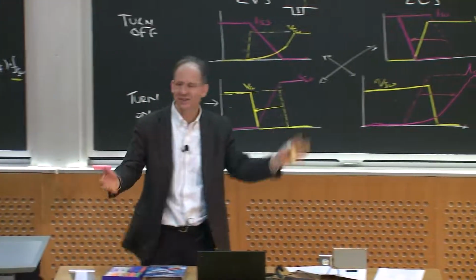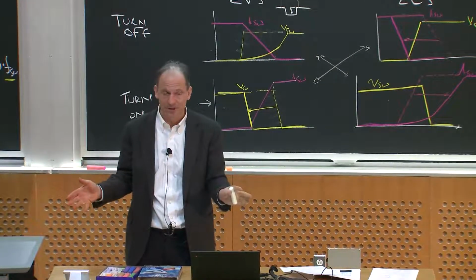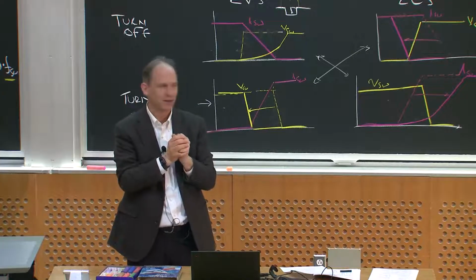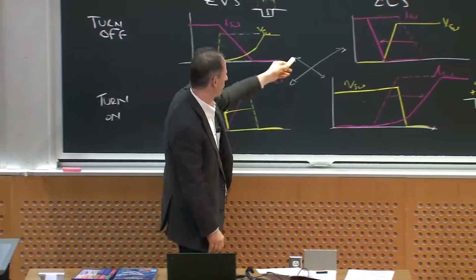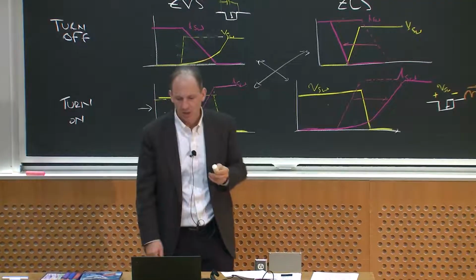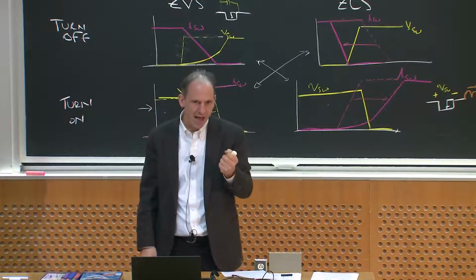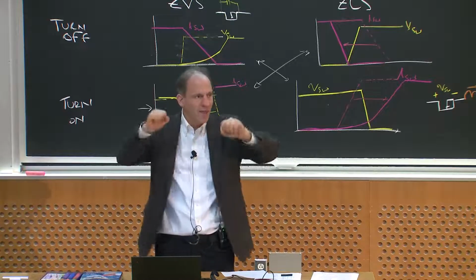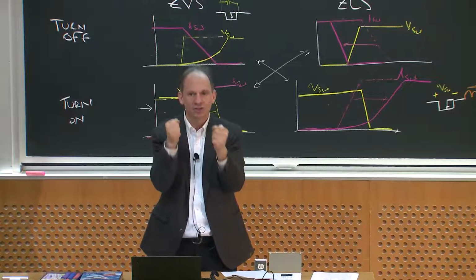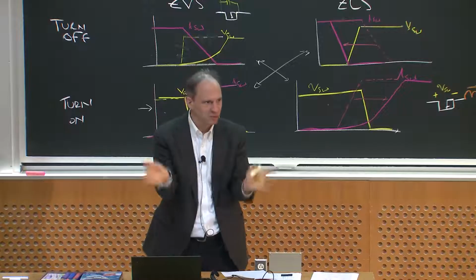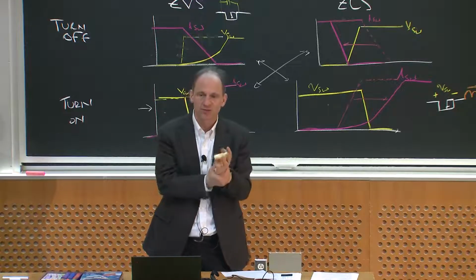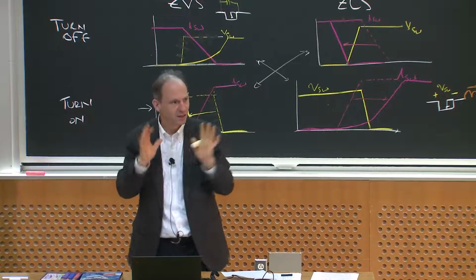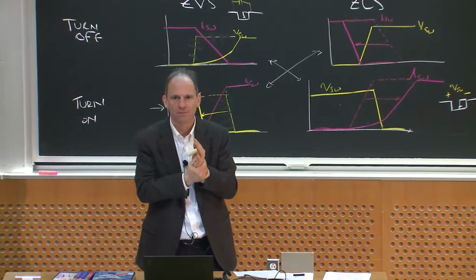There are all kinds of classes of soft switch converter that you can talk about. But a big category is circuits where you design the circuit around getting the magic operating waveform somehow. Another class is: how can I augment a standard PWM converter with some extra circuitry that'll let me run it just like a normal PWM converter, everything we've been doing all semester, but still soft switch the transistors, recover the energy in any snubbing, and still run it like a normal converter?